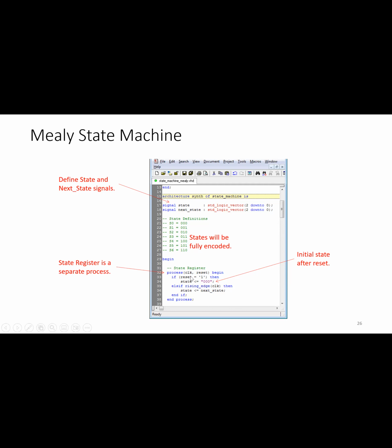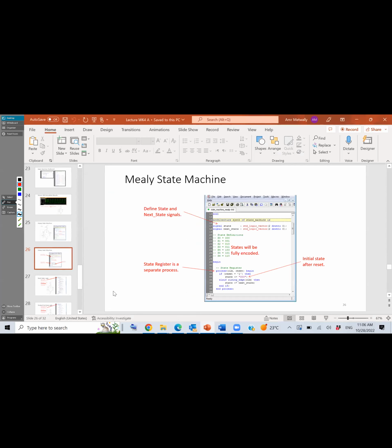Part of it, yes, of course. If I put reset before, and of course, you can see here the reset, when it comes, I didn't say anything about the clock at all. Right. So it's asynchronous. Yes. Okay, perfect. But if you were to put the rising edge first, for example, check for the rising edge, then check for reset. Okay, perfect. Okay, thank you.